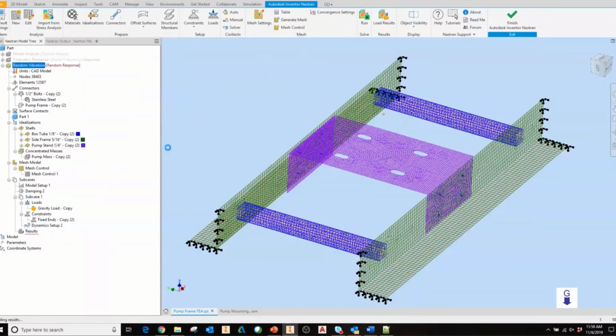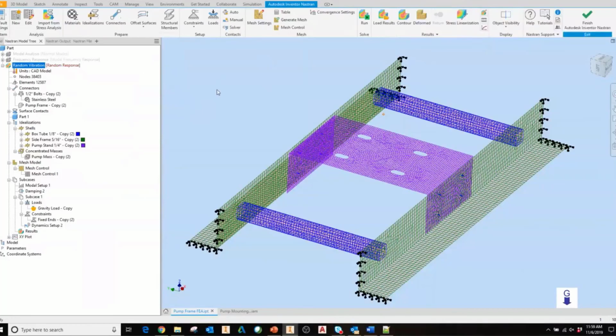And when you run your analysis, I have the setup, everything else is exactly the same as my frequency response. Gravity is still being applied. When you look at your results, you're going to get a list of frequencies. Those are our frequency inputs that we use for basically our modal frequency response, which is run on the front end. You will see PSD scaled frequencies.